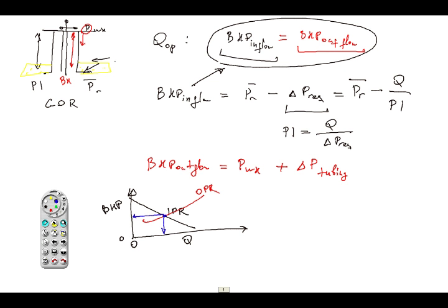So in order to start doing this, we need to plot our IPR and OPR curves first. Let's start with IPR. We know that the PI is linear, so IPR will be just a line here. To draw a line, you only need 2 points. I normally prefer to choose the first and the last point here.